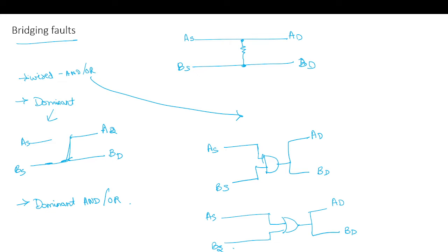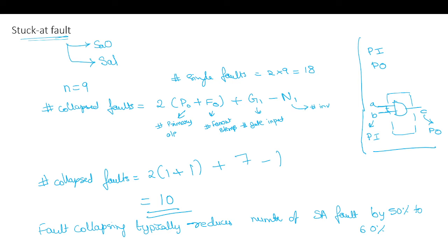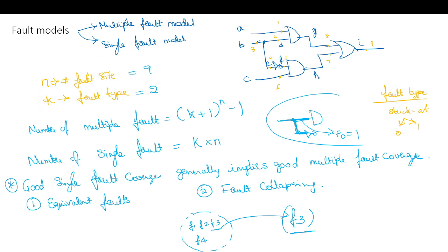No, they are not redundant faults. They are equivalent faults. Say, for example, I get an output 0 here. I apply 0 here, 1 here. This pattern can detect a stuck-at 1 fault here, stuck-at 1 fault here, stuck-at 0 fault here.